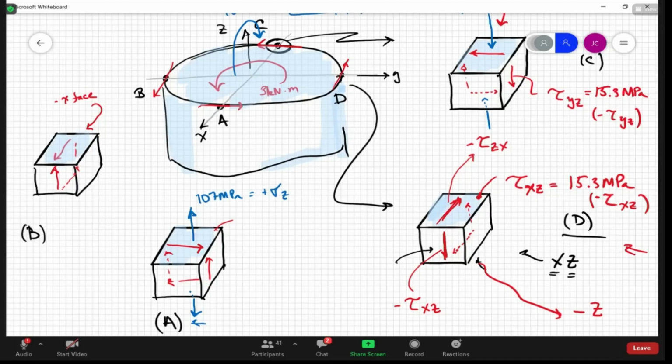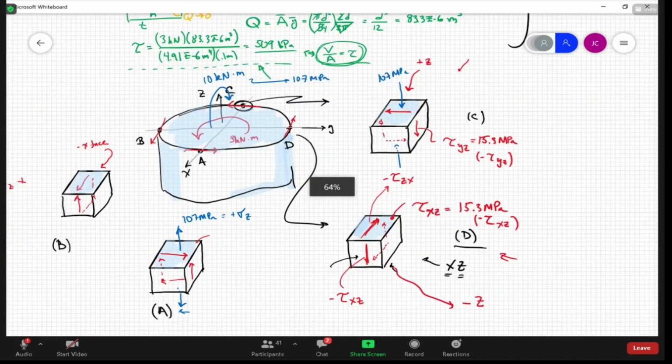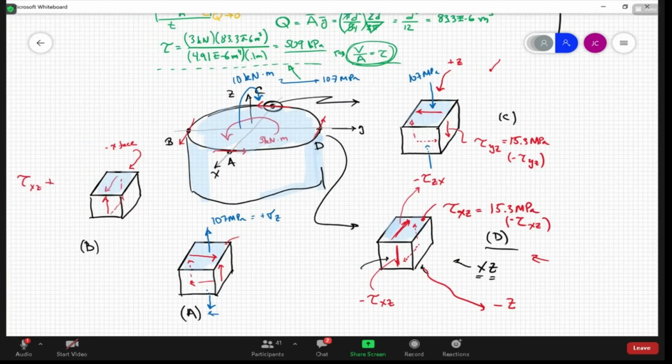So bending stress is a little bit easier, but it's important that you can visualize where it goes to 0 and on which side it's in compression and on which side it's in tension, right? Because if we considered the weight, remember we talked about the weight of the sign, that would have put a P on A compressive stress over that entire face, correct?